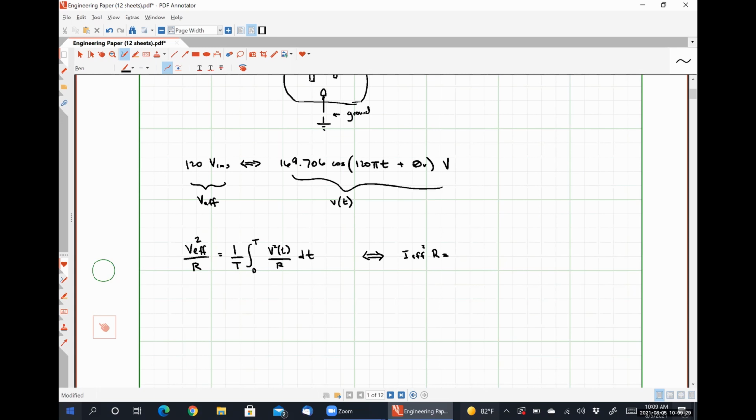So our average power given by a DC current would be 1 over T times the integral over 1 period of i squared(t) multiplied by R dt, which is the exact equation that I derived at the end of class yesterday that we used for those last couple of problems on, I think, homework set 22, I believe. Okay.